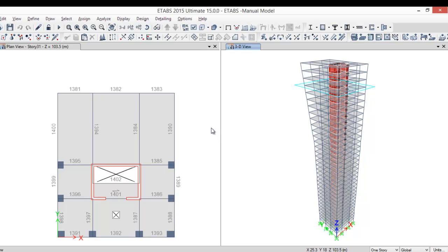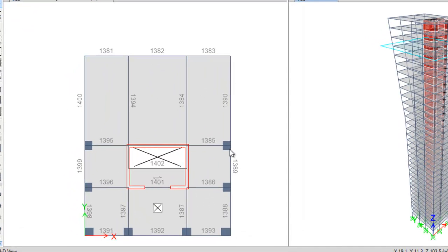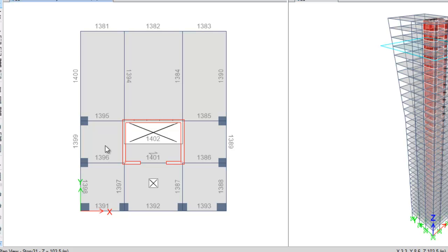The detection is always based on the supports, or actually based on the joints of the beams. If you divide, for example, this beam between two columns into 4 beams, there will be generated a beam with 4 spans, which is more accurate. So it's very important always to connect supports by one element.